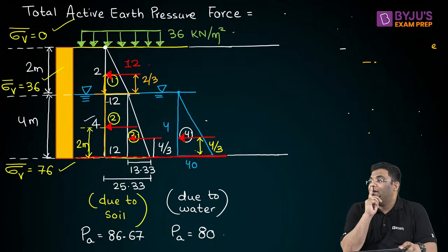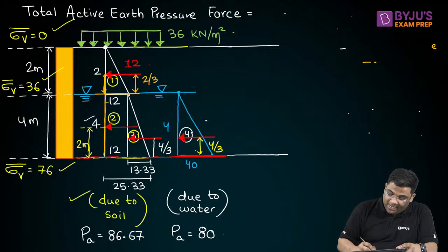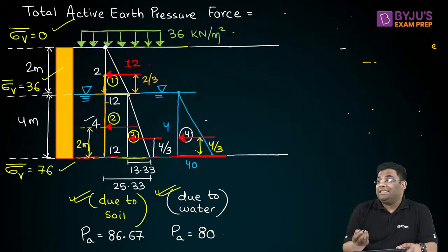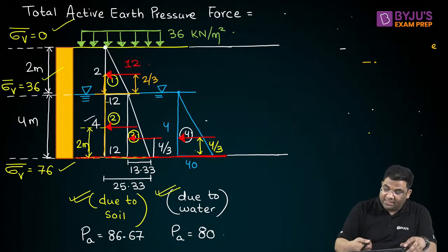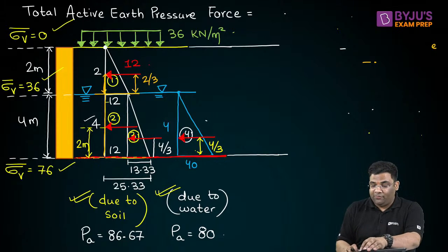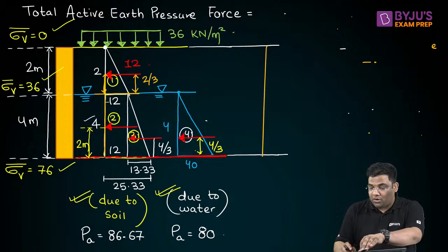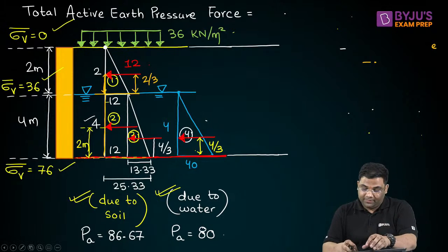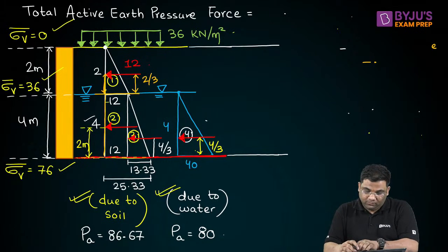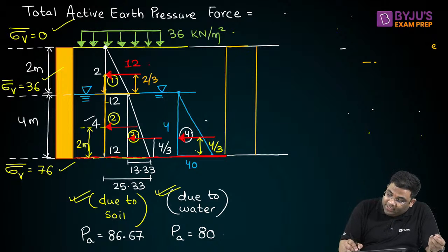Yes, very good, Prince. See, you have already found the force due to soil and due to your water. So you have to just add the force due to surcharge. And we know due to surcharge, I will get a uniform distribution like this. So I will draw the uniform distribution, let me draw it straight.